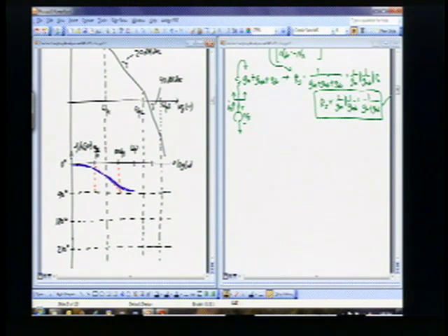So this is omega P2 divided by 10, 10 times omega P2, project these down, draw the asymptote that these correspond to right there, and then I sort of have to mesh these two phases together. So now this phase actually is going to drop down a little faster to go through that asymptote, and we'll do this. Okay, and so on and so forth.